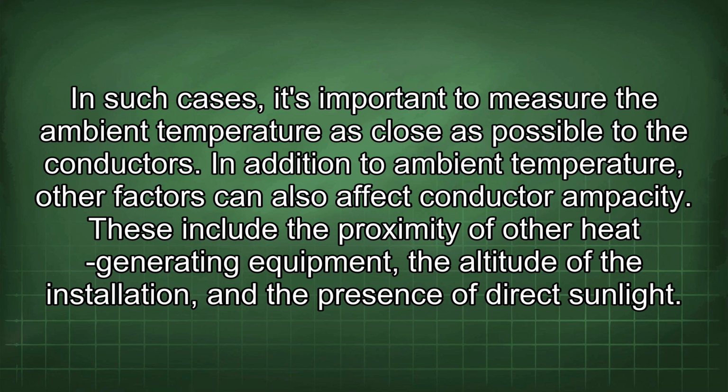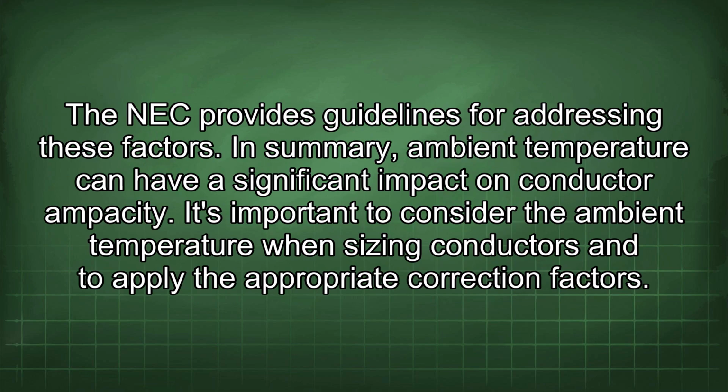In addition to ambient temperature, other factors can also affect conductor ampacity. These include the proximity of other heat-generating equipment, the altitude of the installation, and the presence of direct sunlight. The NEC provides guidelines for addressing these factors.